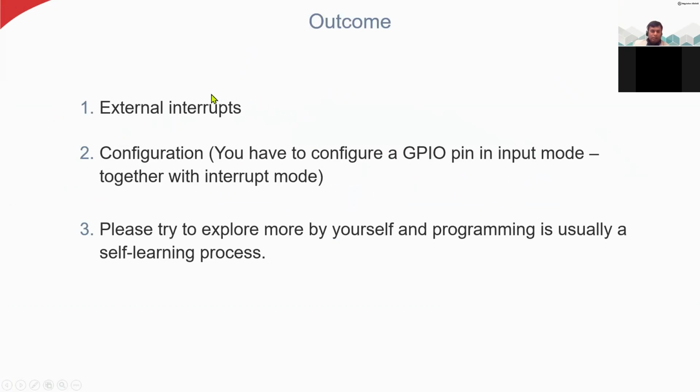So here you will learn a little more about extended interrupts or external interrupts, and you can configure the pin in interrupt mode. So you have to configure a pin in input mode together with interrupt mode. Please try to explore more about this, whatever topic we are going through. Practically, you can explore more in the IDE or whatever tool you are using, either CubeMX or CubeIDE. Try to do this practically so you will not forget it.